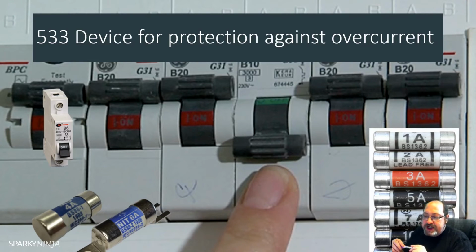533, devices for protection against overcurrent. Let's remember that an overcurrent can be an overload current or a fault current, but this is not an earth leakage current. Compliance with standards: a device for protection against overcurrent shall comply with one of the following. We have a list there of British standards. We have the BS 88 fuse type, such as these. We have the 646, the 1362, such as the plug-in ones there.